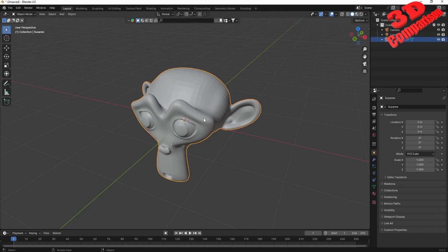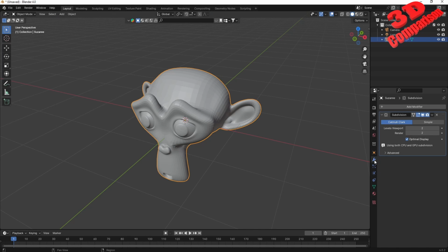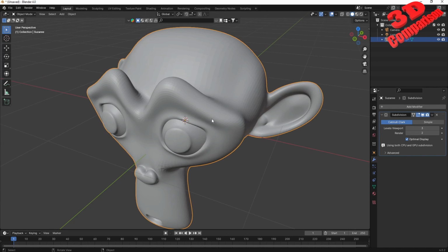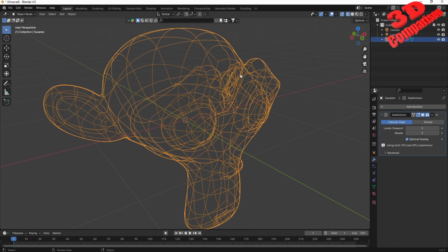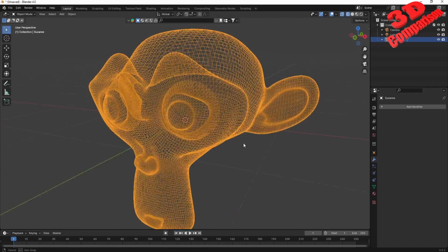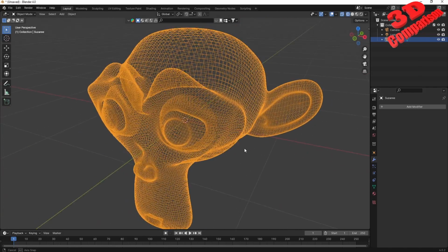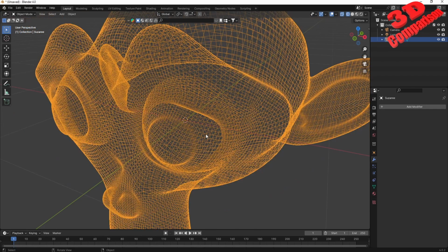But we can just do that within Blender. If I go over here to the modify, have this increase to a different level, for example level 3, and now if I have this re-exported, this will have a denser mesh over here. We can also have this applied, and that will automatically position that. So we see how this is much denser.